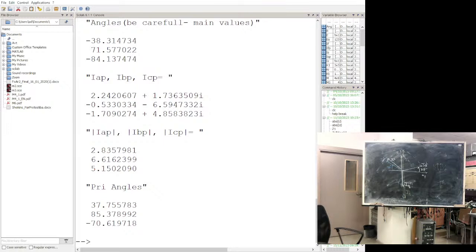Part will go to the customer's asynchronous load. Or if there is, let's say, a cogeneration plant, negative sequence will flow to this plant. But if, for example, they have a solar system, such an effect will not be observed, because the solar system's inverter will not pass negative sequence through. It's important.